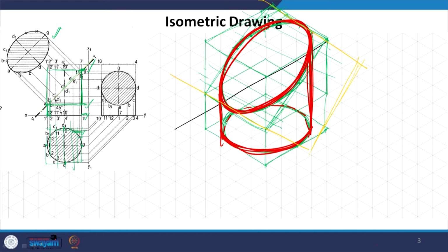So, you can see this clearly here, right. This is the plane which is cutting the cylinder, right. And if I want to hatch it, you will see that this is the sectional surface, and actually the true shape of it is an ellipse, which is this, and which is what approximately you can make a sense out of this, that yes, this is an inclined surface and probably an ellipse.